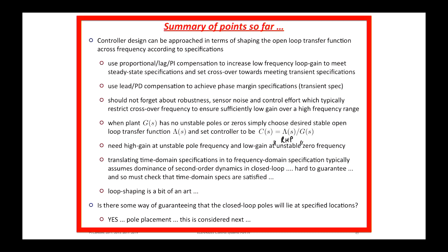Design is not just plugging numbers into formulas. We need to train engineers because there's more to design than just plugging numbers into formulas. Computers plug numbers into formulas better than human beings, so it can't be just about that. All right, but what's important is to understand what crossover means, what phase margin means, what having enough gain at low frequency means, and how that can be achieved by choosing the parameters of particular compensator forms.